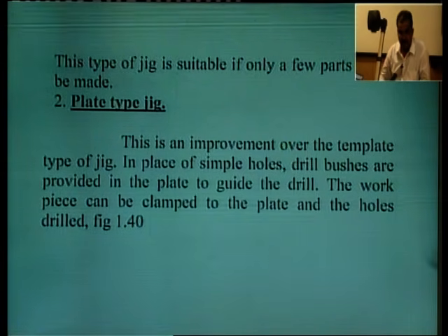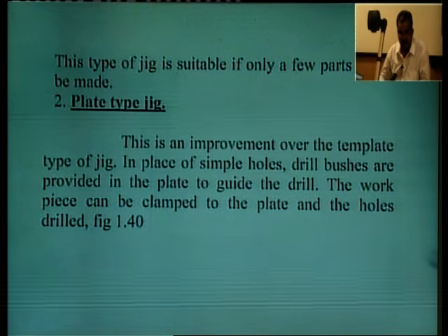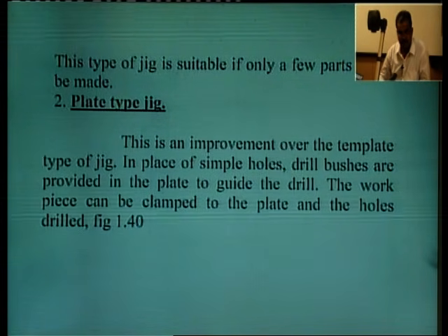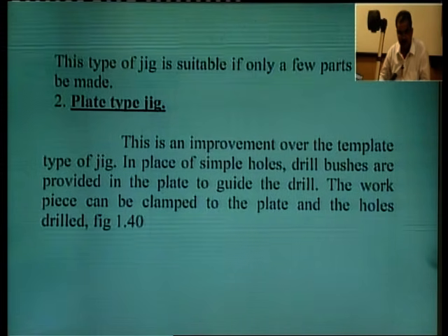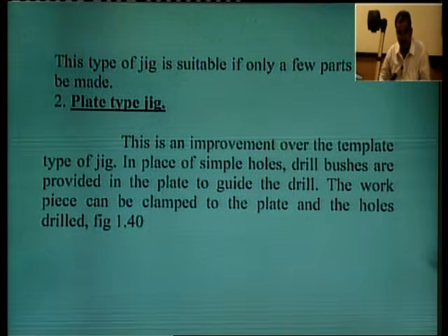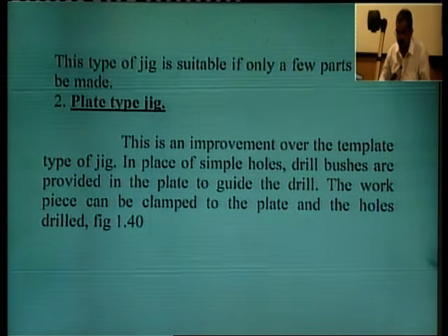This is an improvement over the template type of jig. In place of simple holes, drill bushes are provided in the plate to guide the drill. The workpiece can be clamped to the plate and the holes drilled.